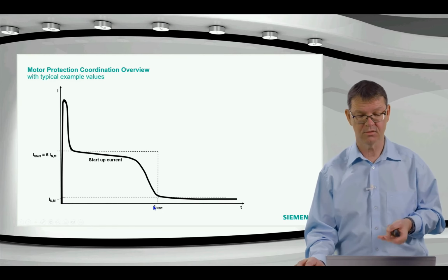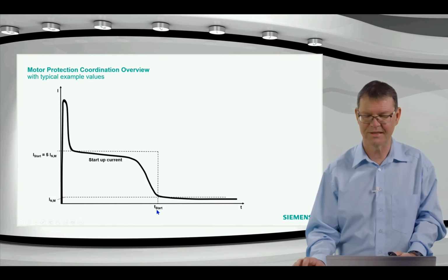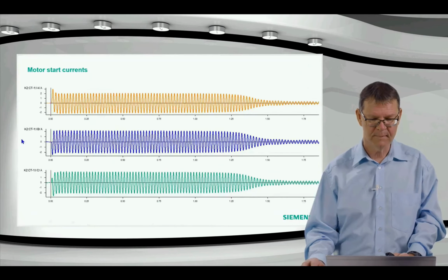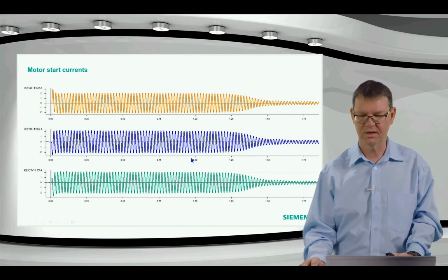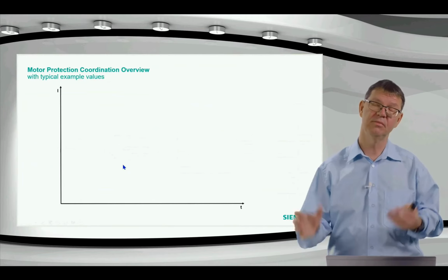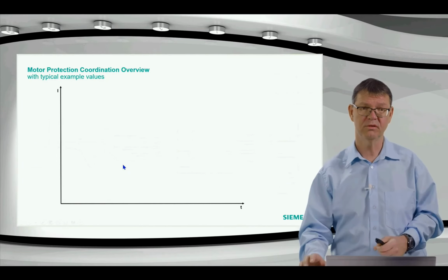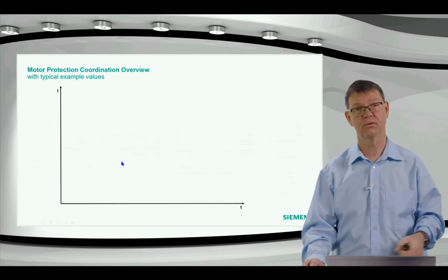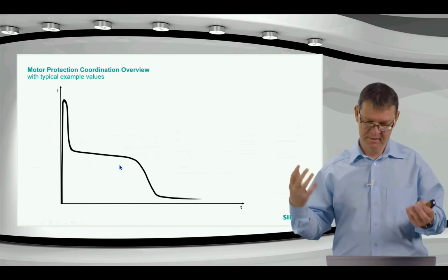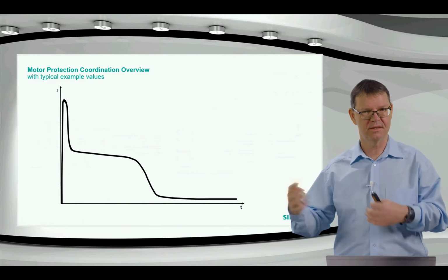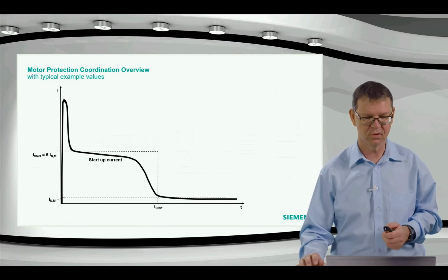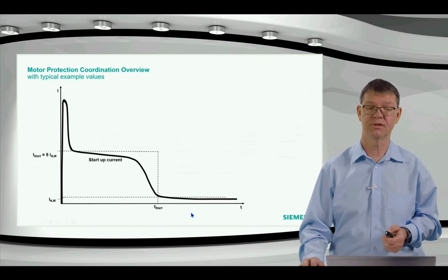And the length, as already, no, we did not discuss about the length. So in the fault record here before, does this come back? We see this is a very fast startup, only a couple of seconds here. If the load is heavier and maybe the voltage is not the nominal voltage, then the startup procedure can also take 20, 30, 40 seconds, maybe longer, even a minute, in that range. So a couple of seconds until roughly to a minute, I think, will cover most of the situations for the length here for the startup procedure.